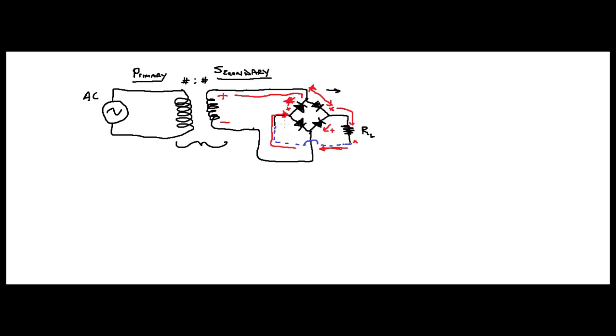The only choice it has is to go this way, doesn't it? And then it's going to come down through this line all the way back home, right? So if you follow that, it has to go through a diode drop right here, a resistor drop right here, and another diode drop right here.